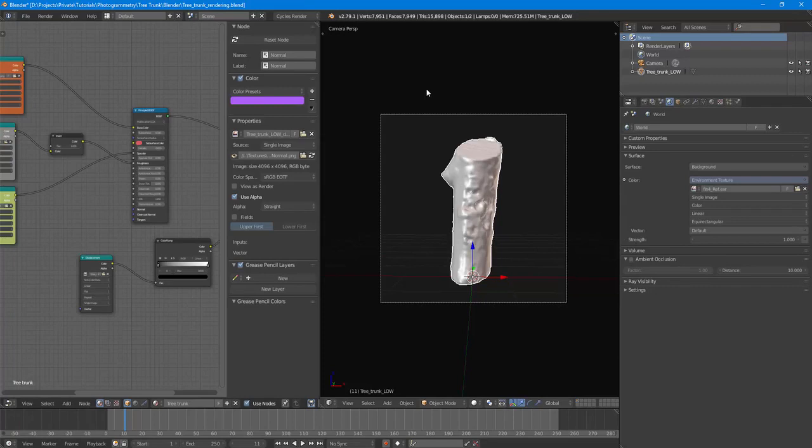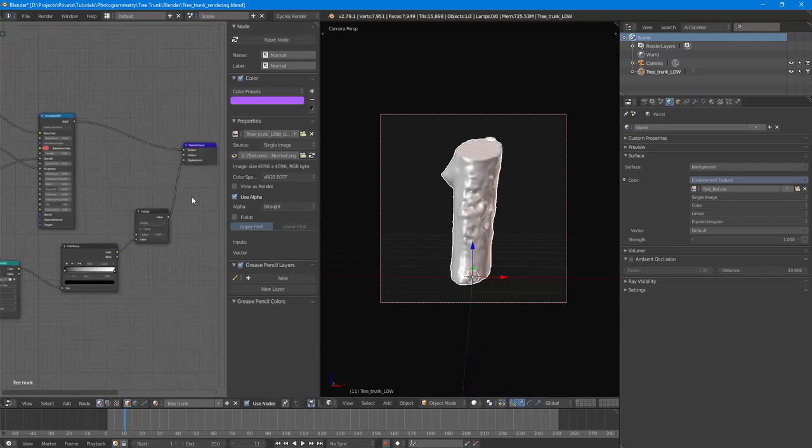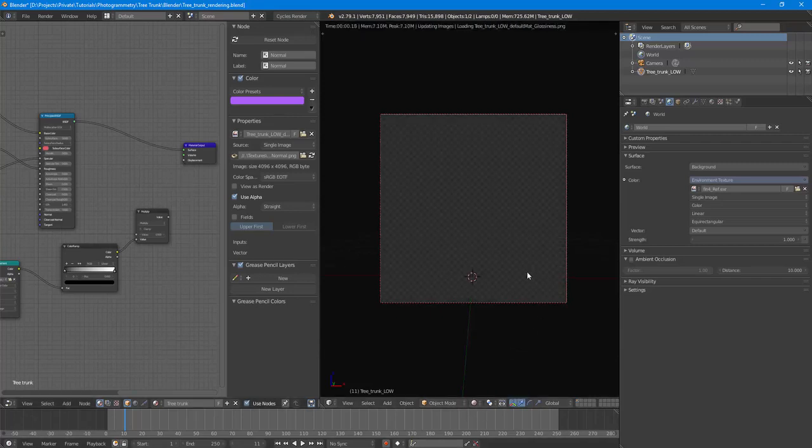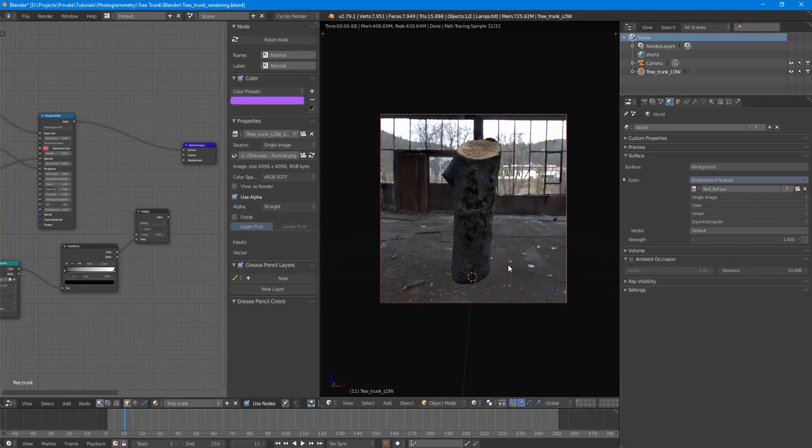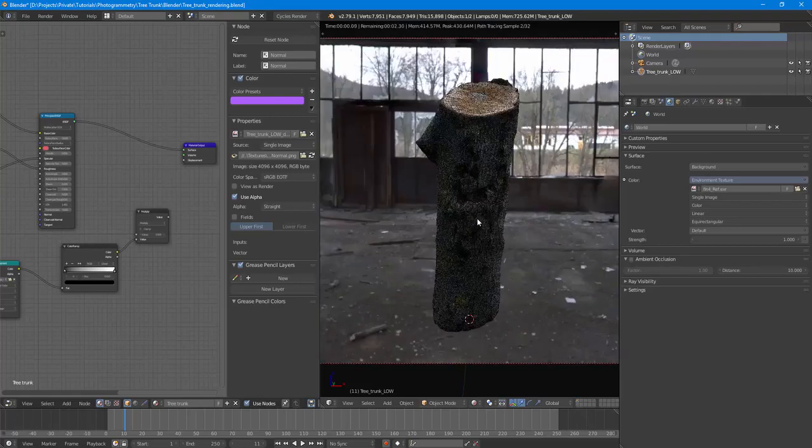And now select Shift plus B, and in the camera view just mark like this to have the border only in the camera view. And now we can take a look. Of course this is now, well, without the displacement, so let's cut it just to see if everything else is okay. It is okay.